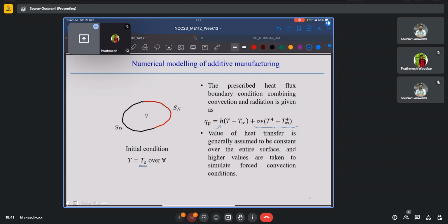And in the model where you actually want to skip convective heat transfer, or where it is too computationally expensive or challenging to model convection, another way to account for the heat transfer by convection is to simply use, say, a much higher value of the conduction heat transfer coefficient to account for the heat transfer by convection, while neglecting the fluid flow.